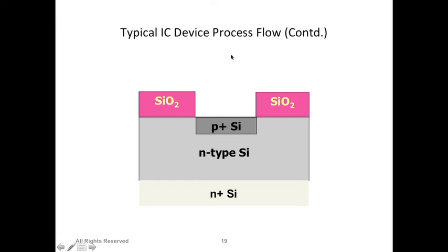Now you can connect the metal with this one, okay? So we can deposit, let's say, aluminum or copper in this case, and then you can make metal lines with photolithography. But if we don't want to deposit on the whole wafer, the whole surface, we can again open a small area to make a small interconnect. So you will see, first we deposit silicon dioxide there.